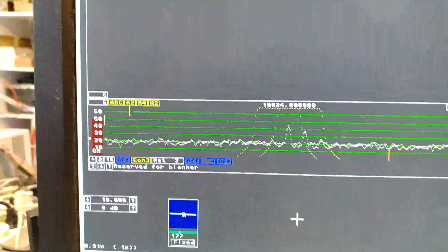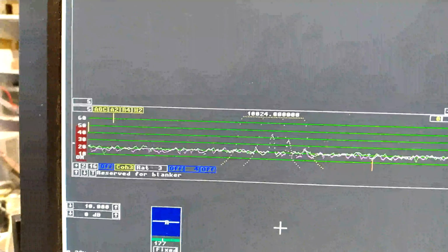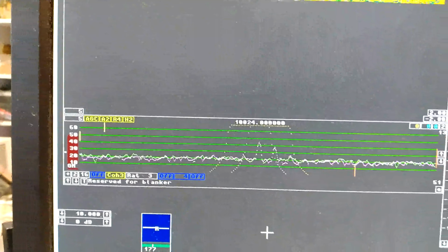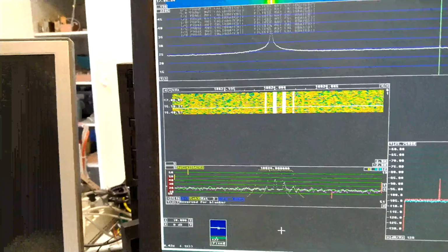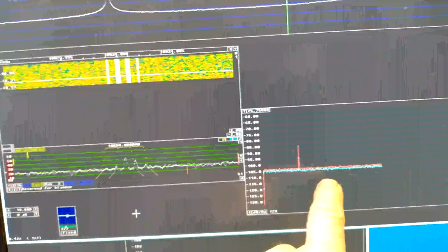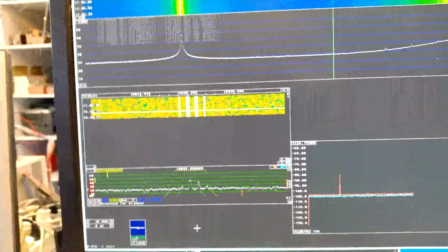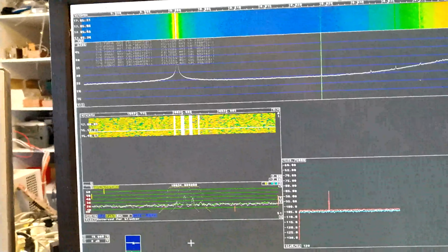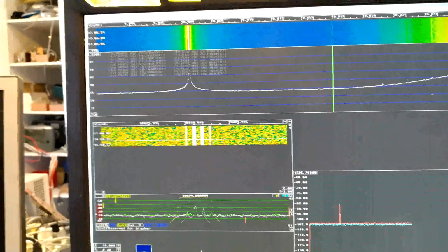I will switch off the signal and see whether it is modulation on the signal or whether it is plain something in the sound card. There is no strong signal present anymore, but the spurs didn't change when I switched off the signal into the receive system. And the noise floor or the signal levels, it didn't change noticeably. So it remains to see whether this signal comes from inside the sound card or from my receive system.